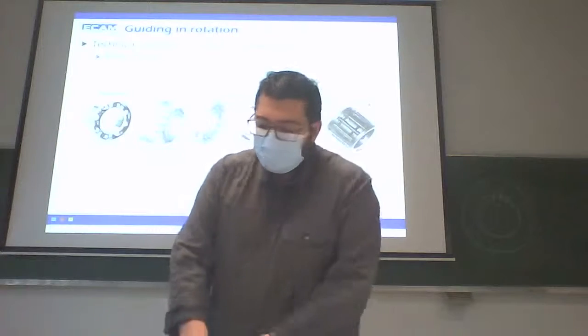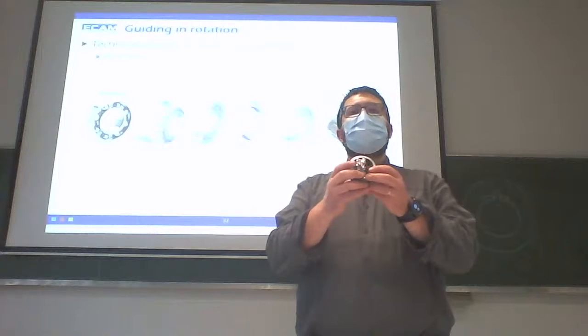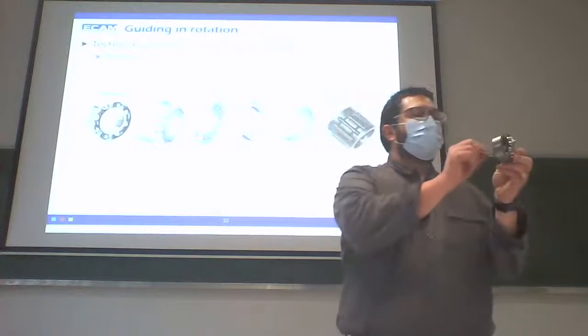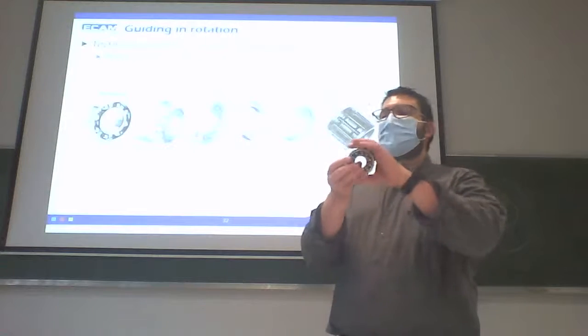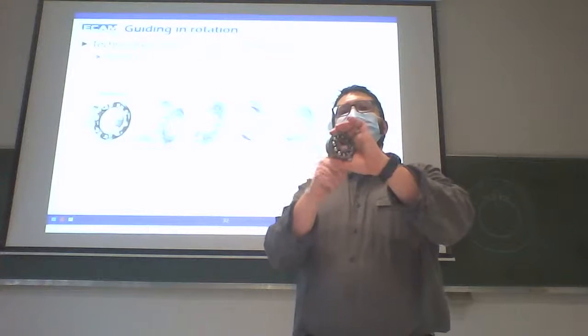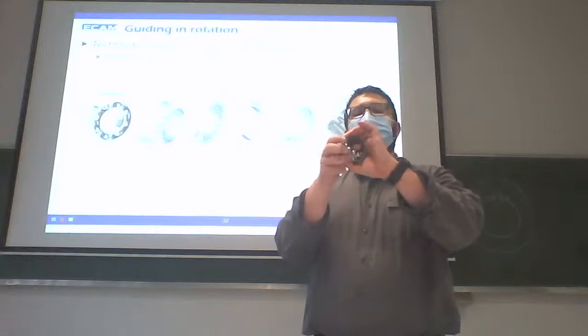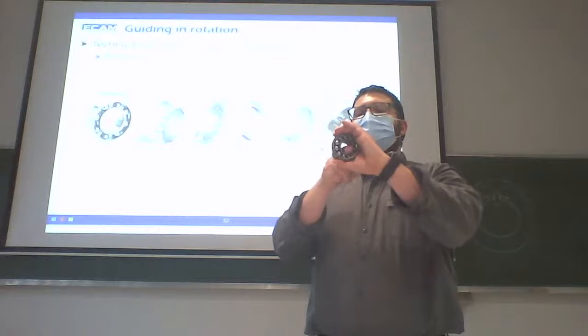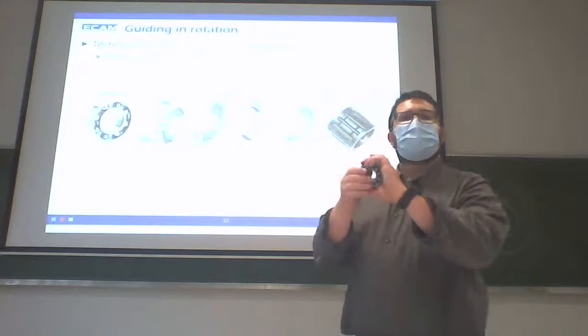You can have a ball bearing with two lines of balls. When we have a ball bearing like this, we don't realize a turning joint, but we realize a spherical joint because we have all the rotations. We have three rotations here: first one, second, and third.